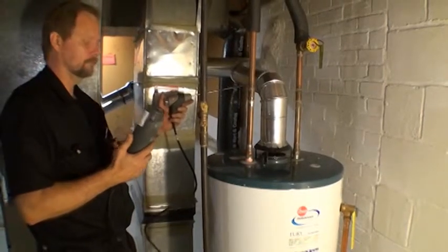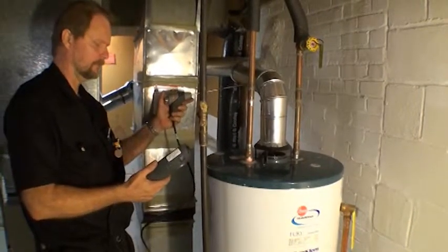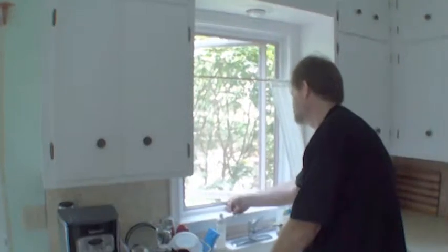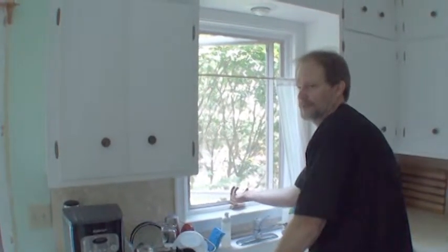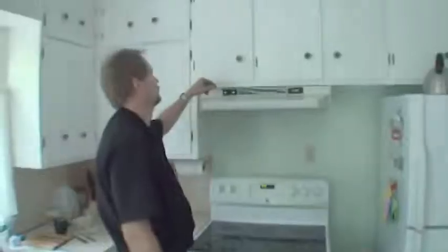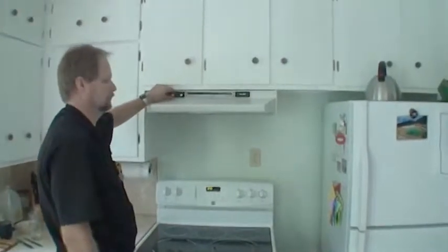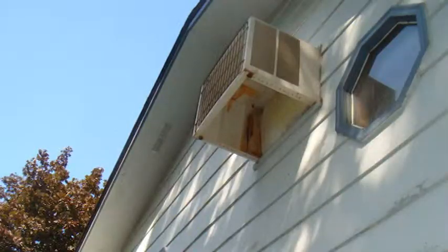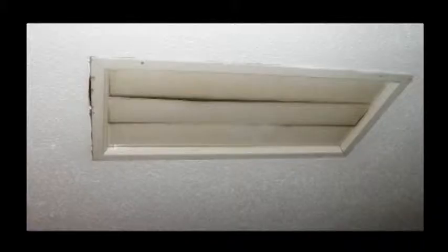The following steps outline the worst-case draft tests. Do not perform worst-case draft tests if wood-burning furnaces, stoves, or fireplaces are operating. Close all windows and exterior doors. Turn on all equipment that exhausts air to the outside, including range hoods, bathroom, kitchen, or any other exhaust fans, and gas or electric clothes dryers. Turn off air conditioners and warm weather whole house fans.